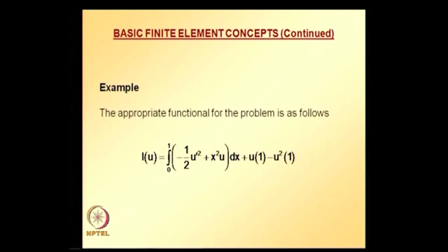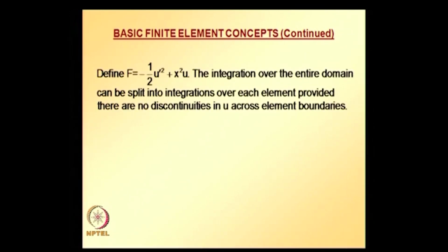And now we define what is the trial solution for this problem in terms of finite element shape functions and the nodal values. Now we are ready to solve the problem that we are looking at. The equivalent functional for the problem that we are looking at, using Galerkin method, variational method, is here. And now into this equivalent functional, you can substitute all the trial solutions.